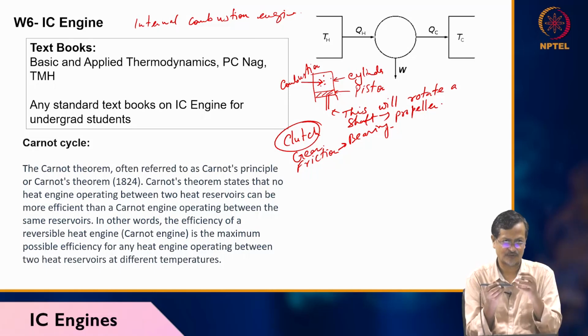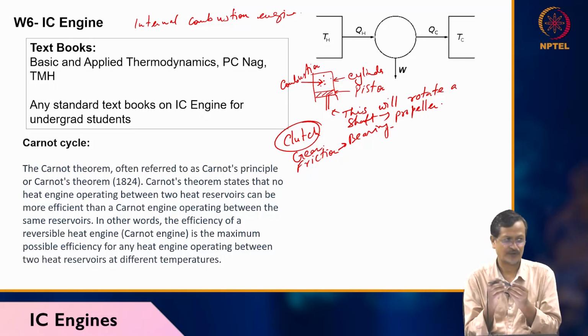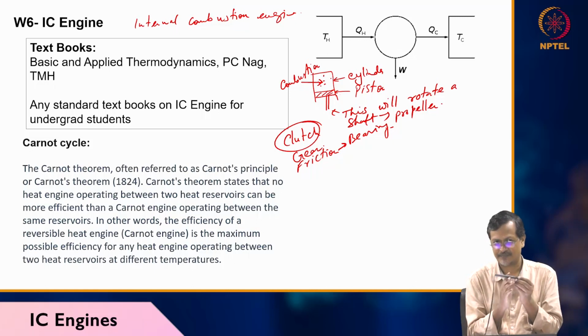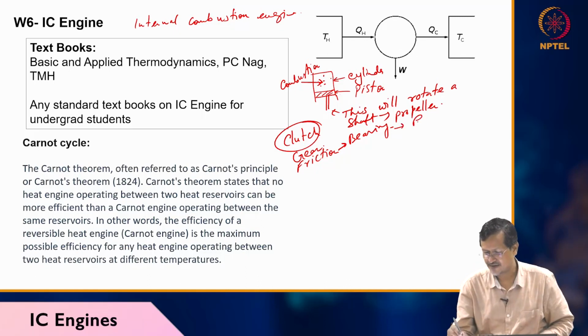The propeller is giving extra axial load, so that must not be transferred to the engine. So then what to do? We must have a certain bearing arrangement called a thrust bearing. The thrust bearing will take the axial load, but it will allow rotational movement. So we will have a radial bearing and a thrust bearing.